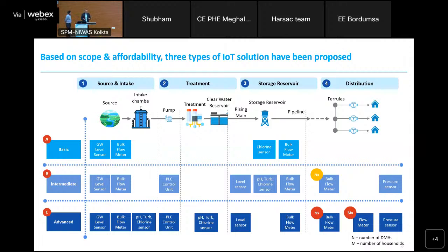That cannot be possible, right? The general trend is 55 LPCD, say 40, 55, 60. Suddenly it has spiked. So that's inaccuracy. Immediately we understood that there is some problem with the meter or some other problem, then we have to go back and check all the steps.